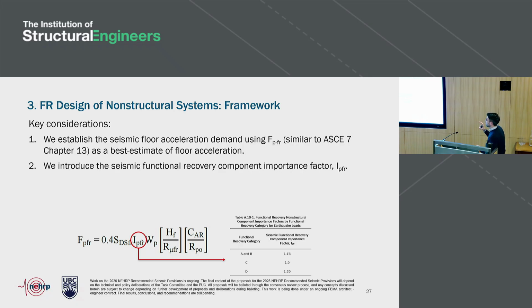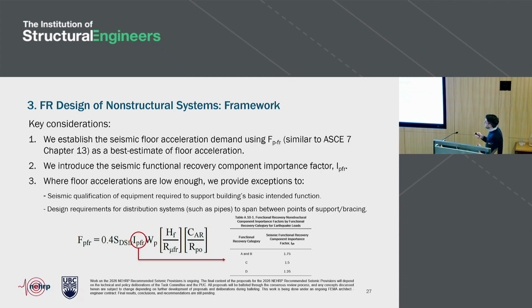And all of this may sound very stringent and potentially well above what we do currently for life safety design. And that's why we introduce a series of floor acceleration thresholds. And we say, okay, if your accelerations are below these levels, you don't need to worry about qualifying your equipment and designing all the non-structural components for these forces, to ensure that we're not introducing something that is just not economically feasible. So that's in a nutshell what you'll find on the non-structural side in these new provisions.